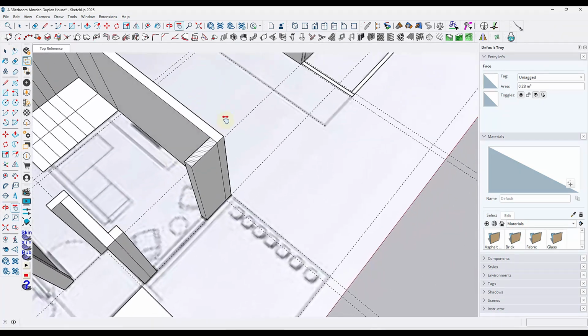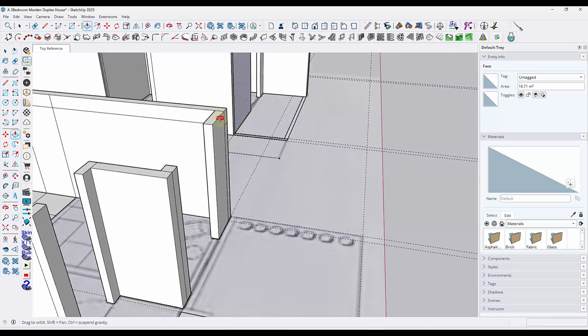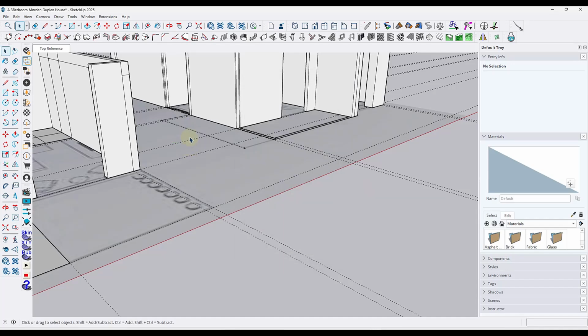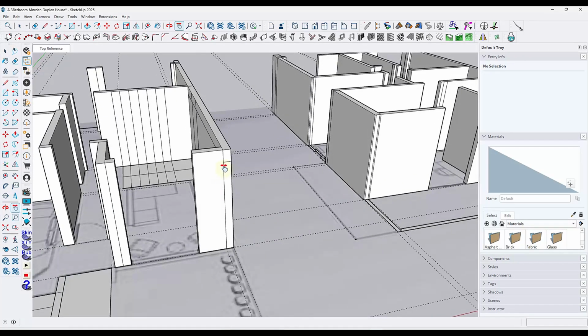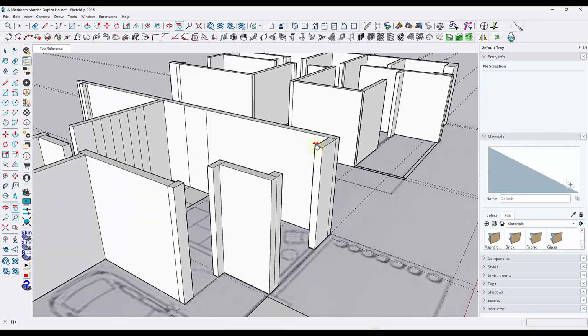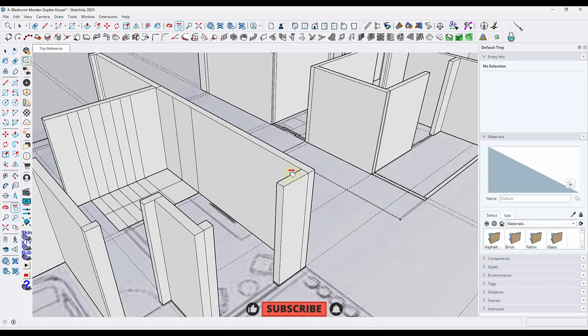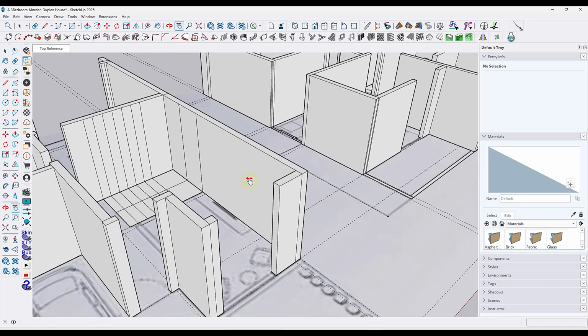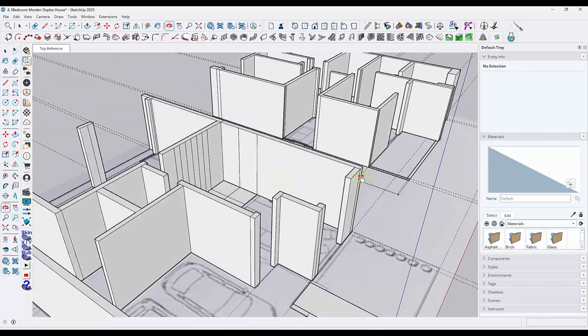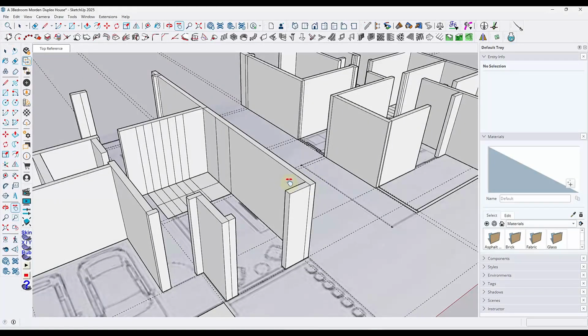The best way to do it is, let's use your select tool. Don't click yet, press Control. You find out there's a plus icon close to the cursor, and you can click the face, go down and type 400. I think we need to go down to, sorry, that's not what I intended. So press Ctrl Z and let's use about 500. 500 seems good, so I'm going to use that. I think that is okay. I'll just use 600. Okay, 600 deep beam, which is not too bad. I think 400 is okay, so let's just go with 500.